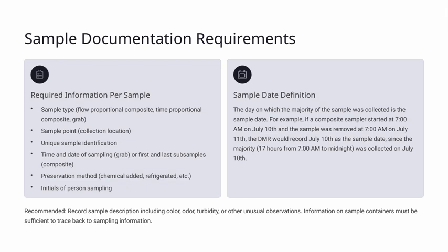For instance, if a composite sampler starts at 7:00 a.m. on July 10th, and the last part is collected at 7:00 a.m. on July 11th, we record July 10th as the sample date because most of the sample, 17 hours, was collected on that day. Finally, I recommend including a description of the sample, such as its color, odor, turbidity, or any